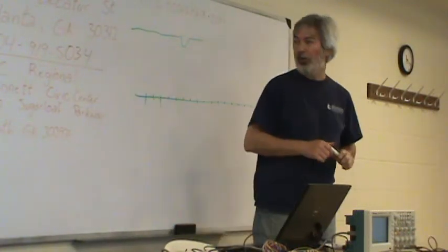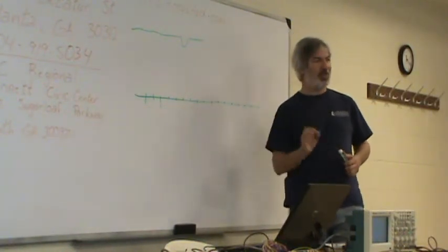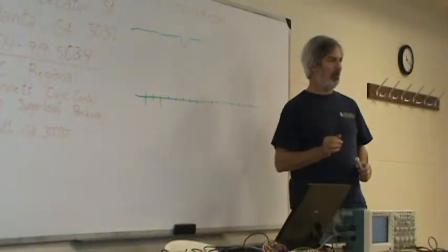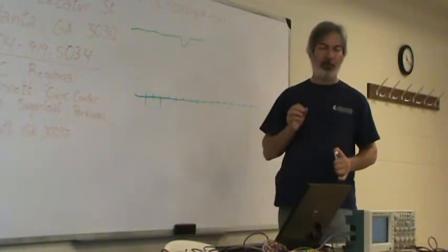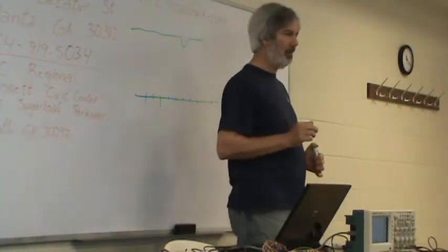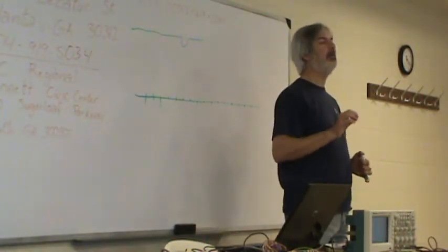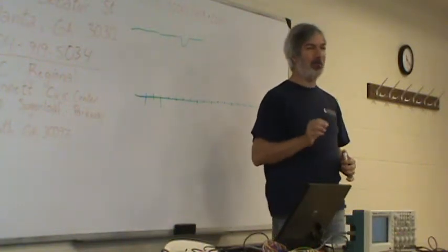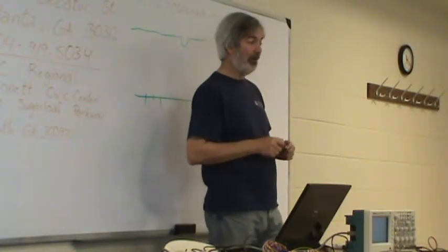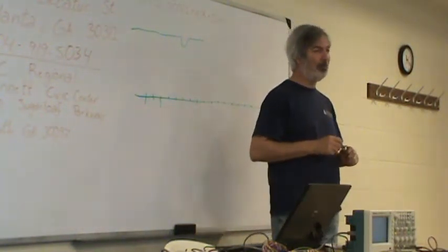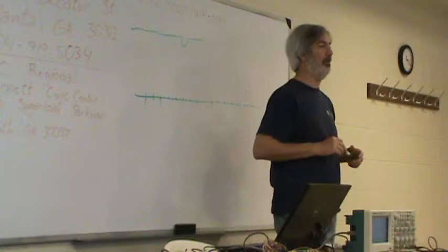And with digital scopes, on a very regular basis, it samples your input voltage. And this works very well as long as you don't have the scope set up incorrectly. If you have a scope set up incorrectly, it will lie to you. This lie is called aliasing. And it's a concept that a lot of people have a lot of trouble with. I did too. I spent a lot of time looking this over and trying to figure out, okay, what exactly is aliasing and how the heck do I explain it to somebody else?